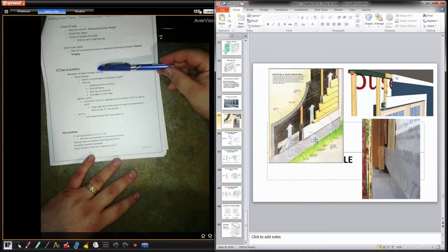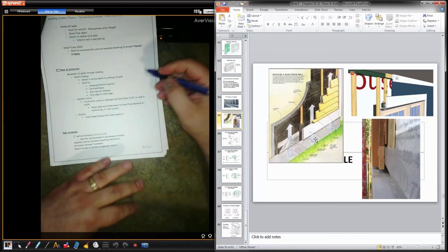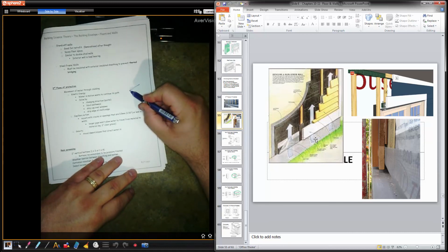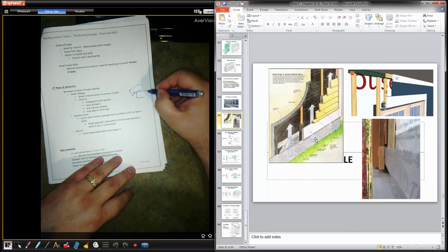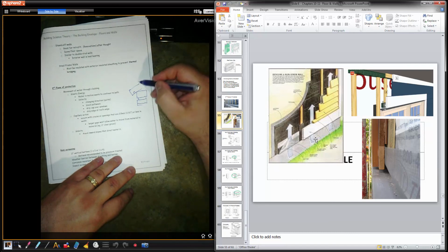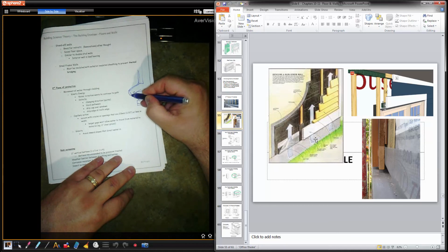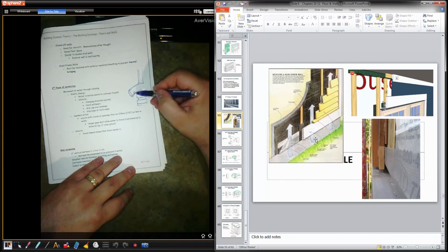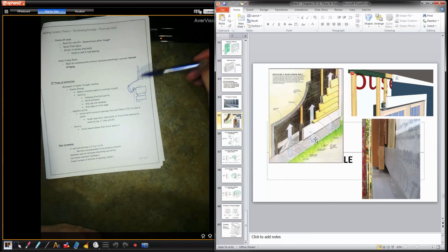So movement of water, so kinetic energy, water motion solved by changing direction. So kinetic energy running down, so if you have a windowsill, a lot of times, so if this could be a brick house, there's your mortar, another brick, there's your window. Water comes down, hits, curls around, that would be a cut on the underside of a windowsill. Whenever water hits that cut, water then drops. So that's kind of how we deal with kinetic energy around a building.